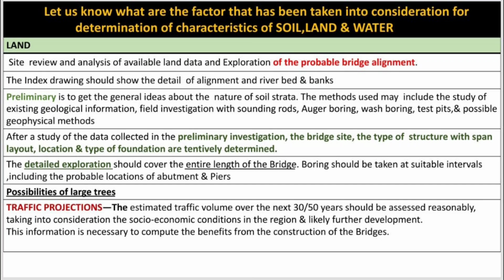The estimated traffic volume over the next 30 to 50 years should be assessed reasonably or may be decided by the authority, taking into consideration the socio-economic conditions in that region and likely further development and possible connectivity. This will reduce the change of scope in the contract. Change of scope is the second major point in the EPC contract.